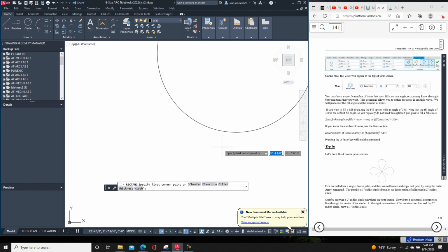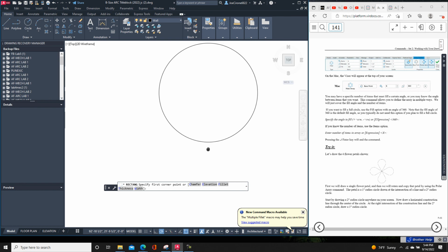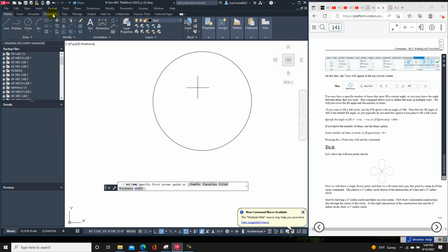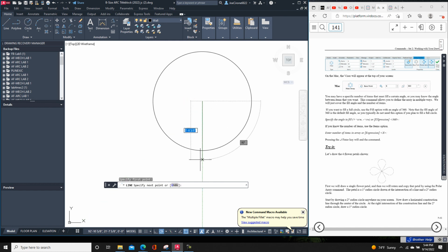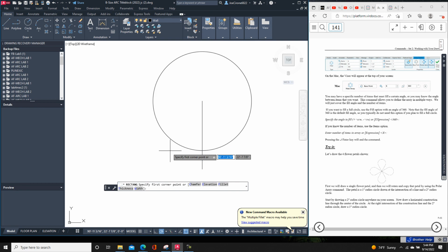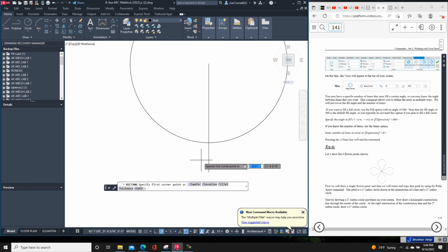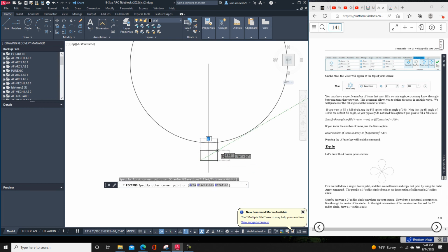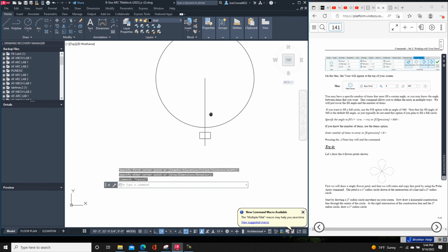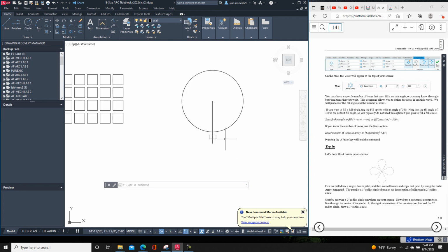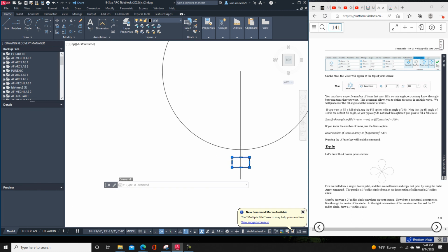What you want to do when you create the geometry for something like that is you oftentimes will want to make a construction line so that you can center that. And I'm just going to do it by eye, but if I was wanting this to be perfect, I'm charging a lot of people for dinner at this wedding, then I would draw half of it and mirror it. But so this would be a chair, and then let's make that a little bit bigger.